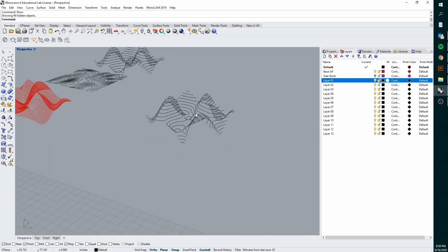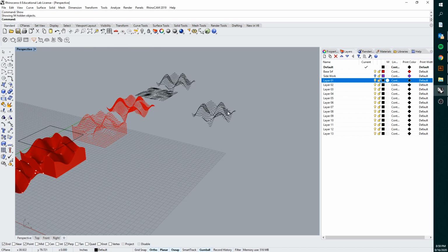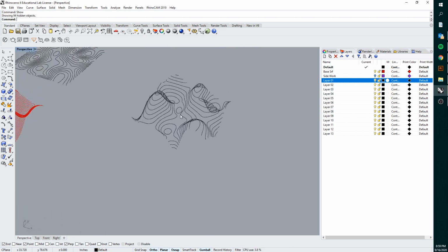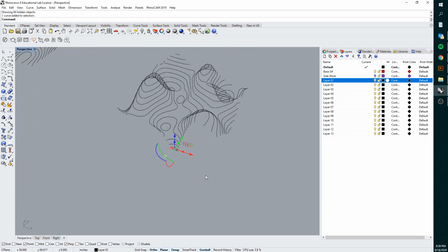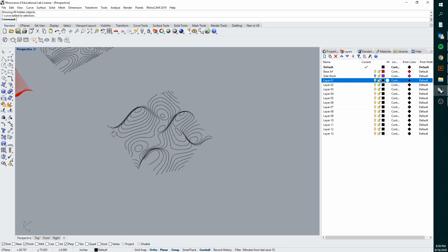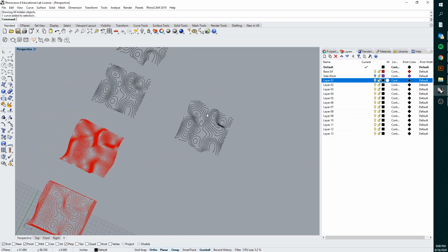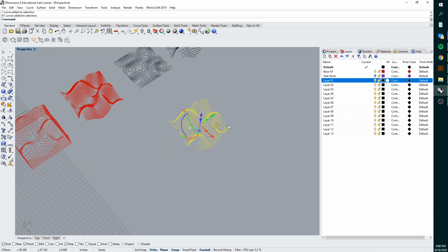So now if we wanted to construct this into a full 3D model that simulates this type of geometry, what we're going to need to do is take, basically, this is our bottommost layer. So we're going to need to make a rectangle around that to make basically a base plane for this. So how would we go about doing that when we don't have any corner anchor points here? We're not really sure how big our site actually is. So if we highlight all of this and we do a bounding box, the command there is bounding box.